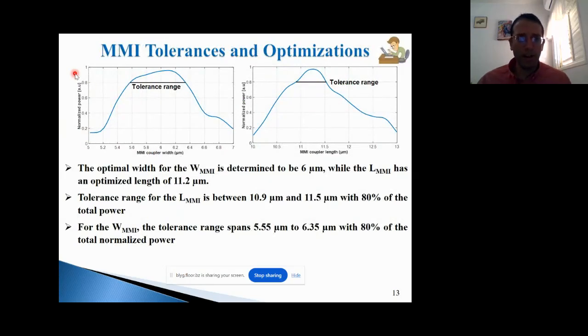And of course, this is also explained, so we can continue. We continue to do the tolerance range using the RSoft beam propagation method. We also use the full vectorial beam propagation method. And we also use MATLAB script and Python script combined with our model and AI to boost and find a better solution, with more accuracy, for an MMI suitable to multiplex 4 wavelengths. So this is the optimal width of the MMI, with a large tolerance range. It's 11.2 micrometers, as we can see here.